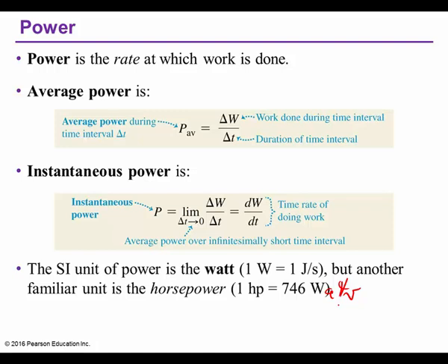Probably average, won't it? Because what's going to happen to that meter? It's going to fluctuate, isn't it? Has anybody ever done that? Anybody ever watched a VOM meter? You don't get straight 120 all the time, do you? If you stick a VOM meter in one of these outlets, it'll probably hit 120 and then drop down to 118, and it might go up to 121 and drop back down to 119. Might even drop to 115. And if it gets down to 110 or 105, we've got a problem.